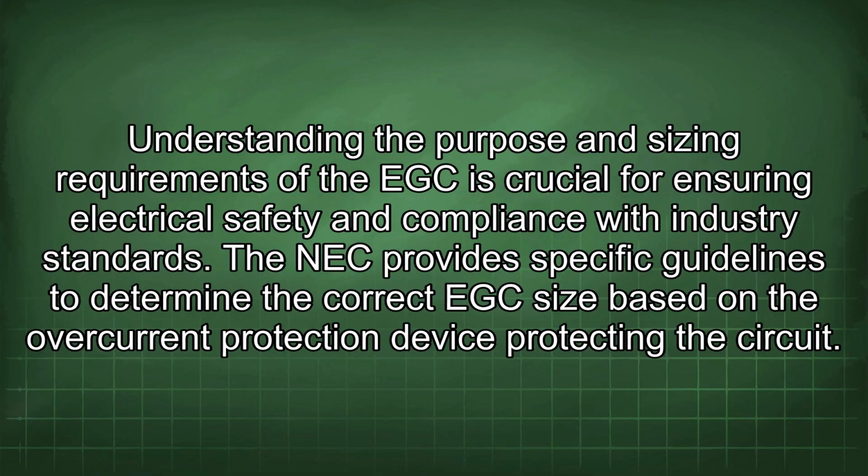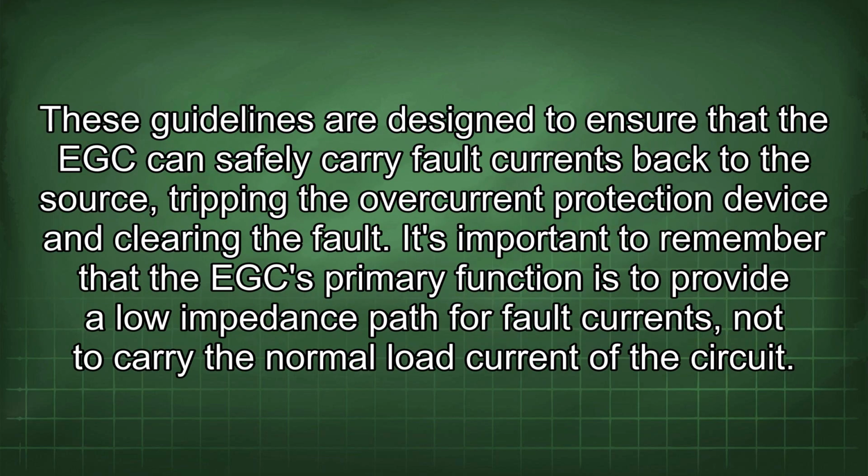The NEC provides specific guidelines to determine the correct EGC size based on the overcurrent protection device protecting the circuit. These guidelines are designed to ensure that the EGC can safely carry fault currents back to the source, tripping the overcurrent protection device and clearing the fault.